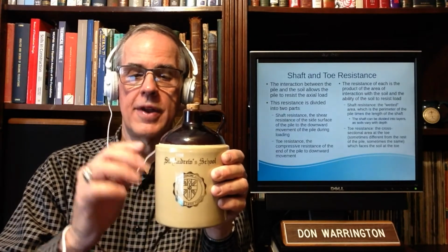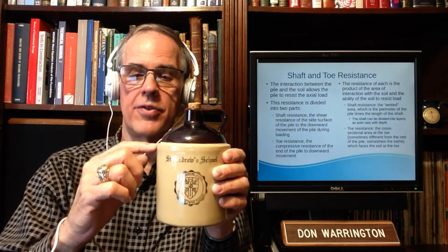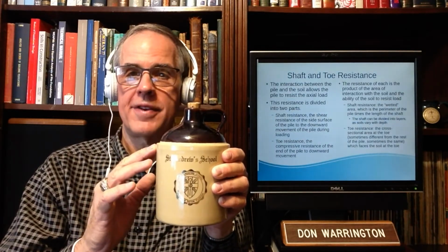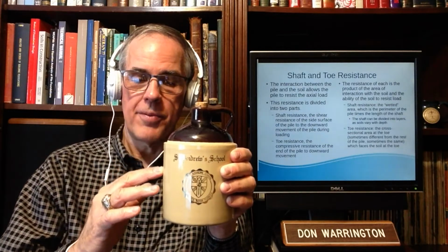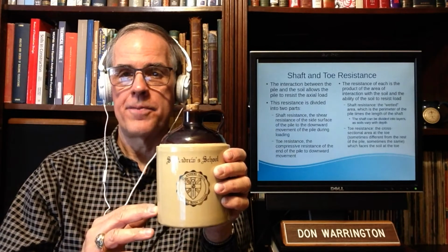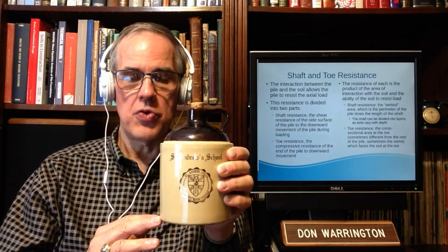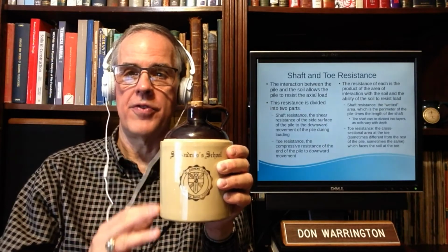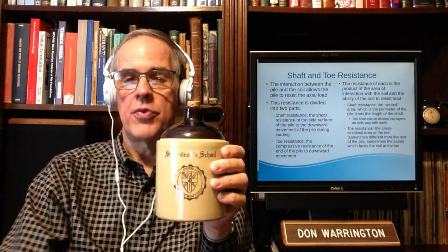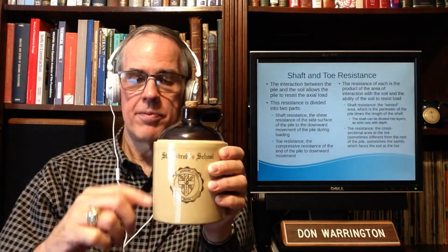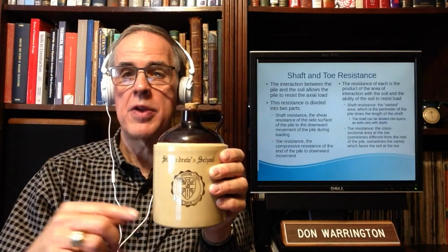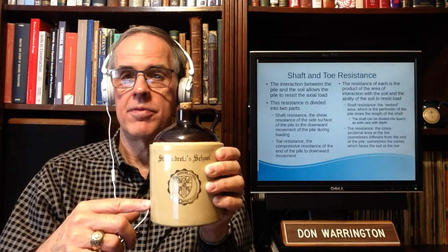say I've immersed it up to this rim, the soil at the top will go plastic first. As I further push on this thing, the elastic will go down, and eventually you will have all the shaft resistance. If I put enough load on it, the shaft will eventually load up completely and be all plastic. At this point, I say that I've completely mobilized the shaft resistance.